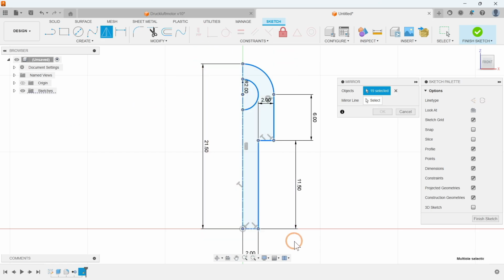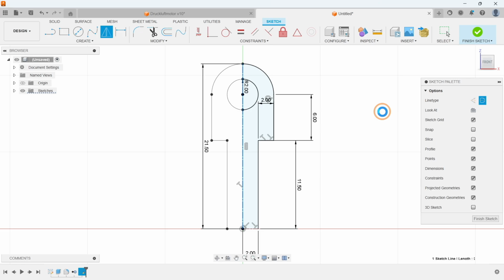At this point, we should definitely click on the center lines again to deselect them. Otherwise, they will be duplicated at the same position by the mirroring. As the mirror axis, we select the previously created center line on the Z-axis. After selection, we confirm the process with OK.